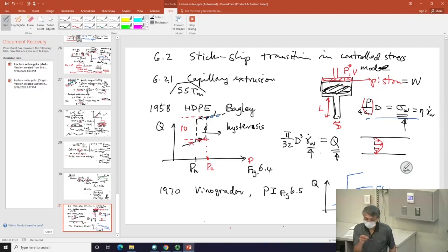In other words, what is making a transition, makes such a big change? What happens is near a critical pressure, all of a sudden the material becomes 10 times or even 100 times faster. With rubber, he can find 100 times. We later could find 1,000 times faster. No sweat. At the same pressure, all of a sudden, the material that was initially coming out slowly immediately comes out much faster by many orders of magnitude.